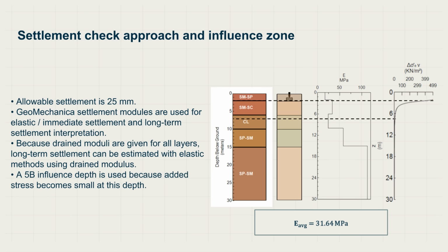Finally, we perform the settlement check. We model long-term settlement using drained moduli over an influence depth of 5 times the footing width to ensure we remain under the 25 millimeter limit.